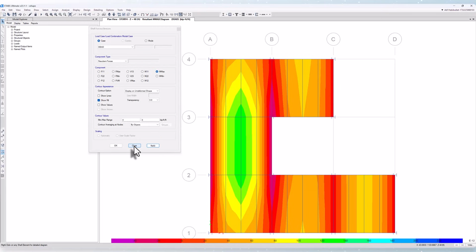A couple other notes about the primary differences between rigid and semi-rigid diaphragms. In relation to eccentricity, for rigid diaphragms, the accidental eccentricity associated with auto seismic loading is concentrated and applied at the center of mass, whereas for semi-rigid diaphragms, accidental eccentricity is applied to every node for auto seismic loads. And if no diaphragm is assigned, eccentricity will be applied to any node.